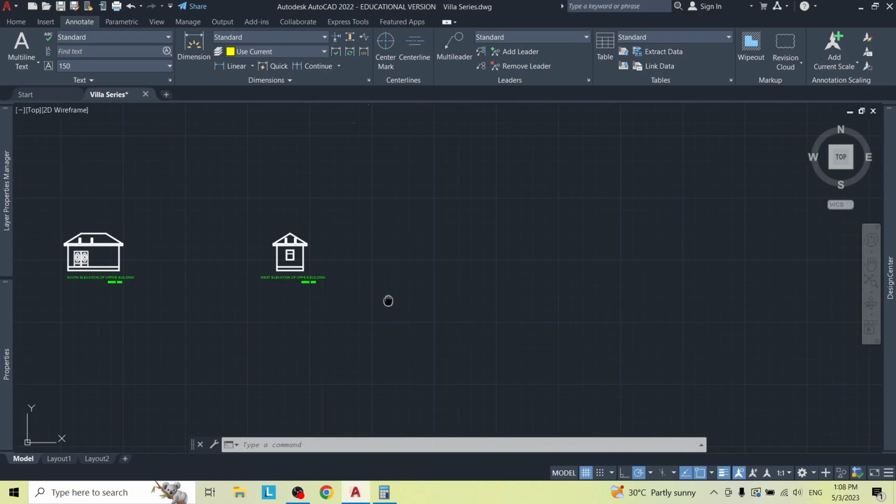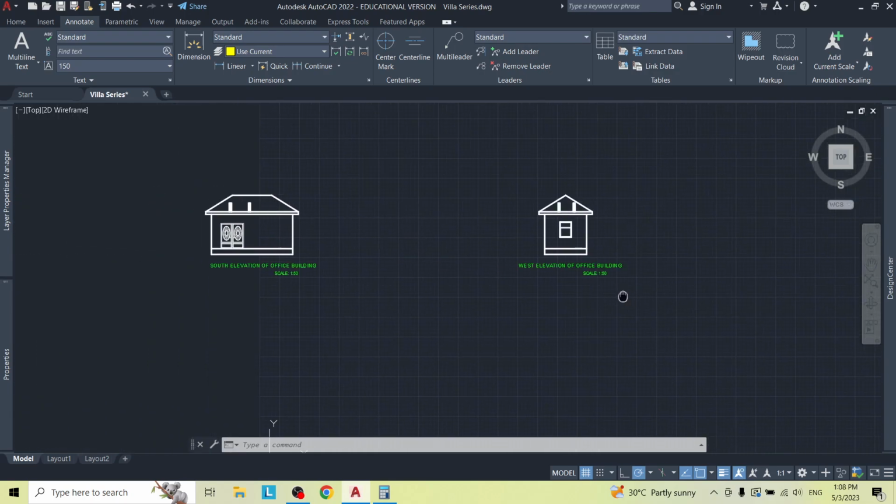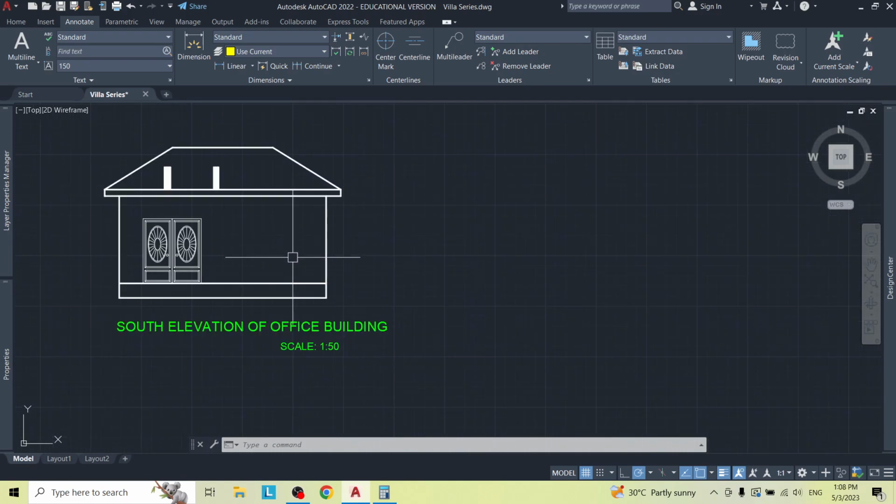But yeah, so just remember when you're doing the elevation drawing, with this method, you want to put your ground line, then you put the floor of the house, right? And then you're going to offset the height of the bottom of your fascia board, and then from that line offset 5 feet upwards, right?